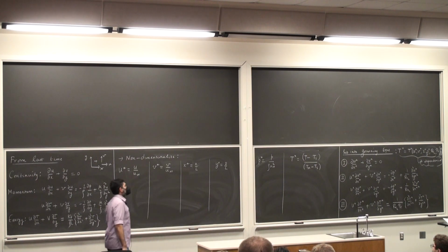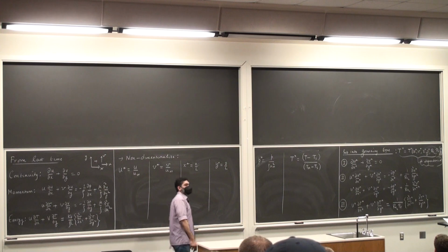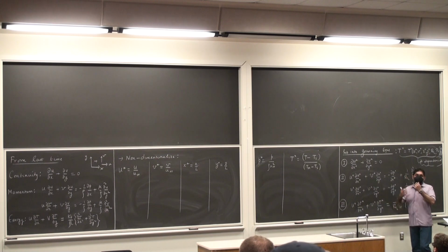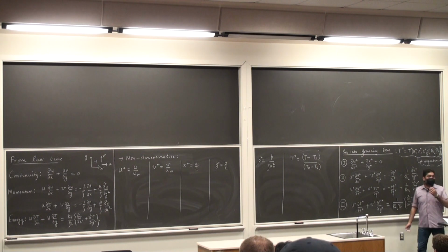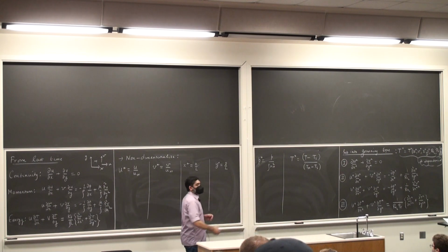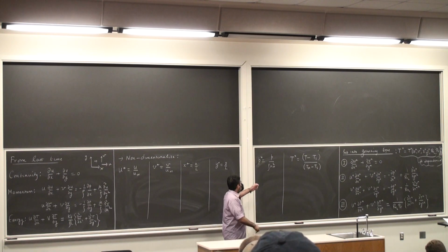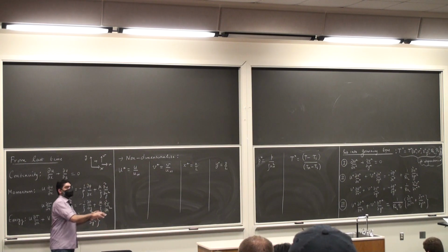Alright, so the culprit here is this pressure term, because we have no idea what the pressure is within the boundary layer. Outside the boundary layer, of course, the pressure is free stream pressure, P infinity, the flow pressure that is prescribed to begin with. But within the boundary layer, this can fluctuate wildly. The fluctuation of the pressure is the cause for, in many situations, transitions from laminar to turbulent flow, as you might know from flow past a cylinder and so on from fluid mechanics, and even flow past a flat plate. So, by hook or crook, I want to get rid of this guy from my equations. And that is the whole plan for the next 15-20 minutes.